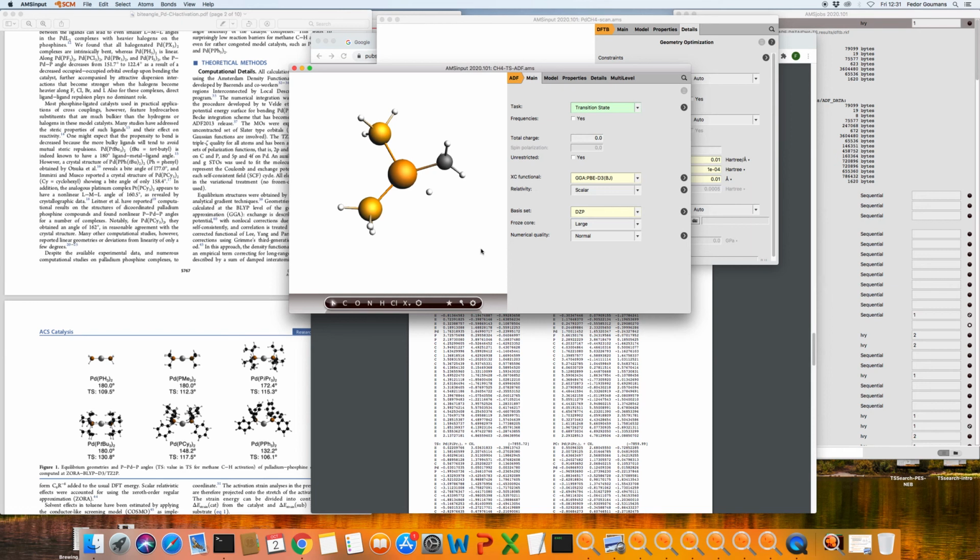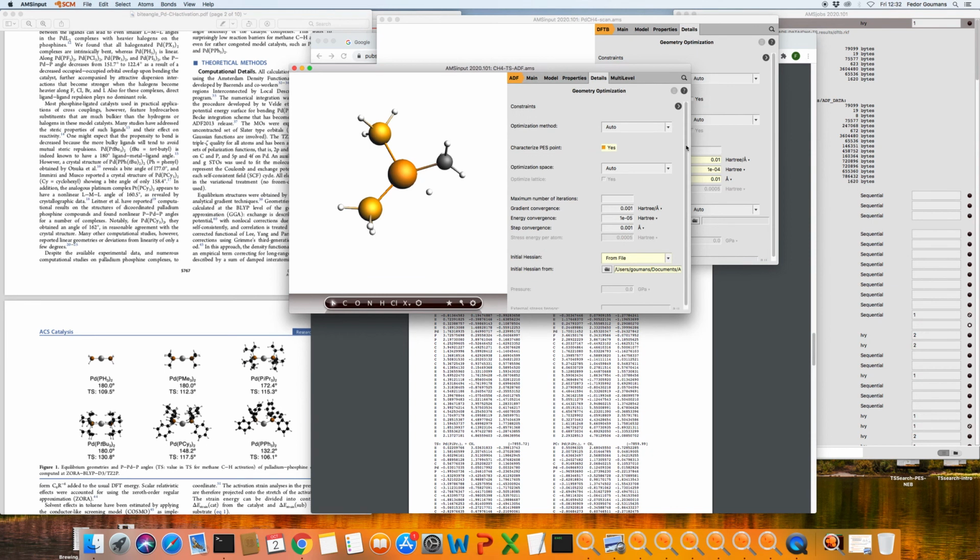Now of course we're not certain that we have the same numbering of the atoms here, so if we want to use a DFTB Hessian we actually have to calculate it. So if you remember, that could be done here by choosing calculate with fast engine, defaulting to DFTB in this case. Now if I save this as CH4 TSADF from coords,